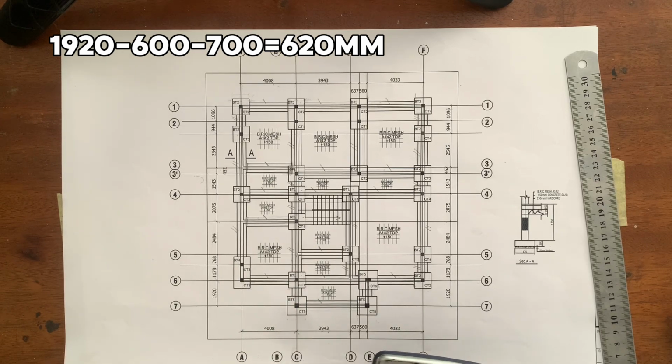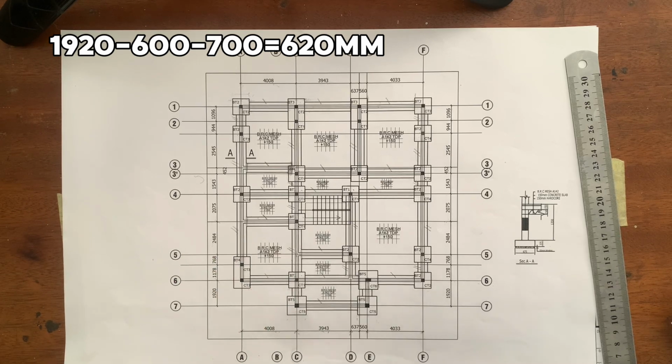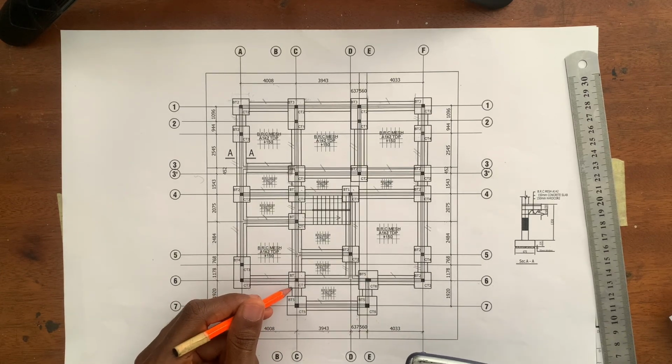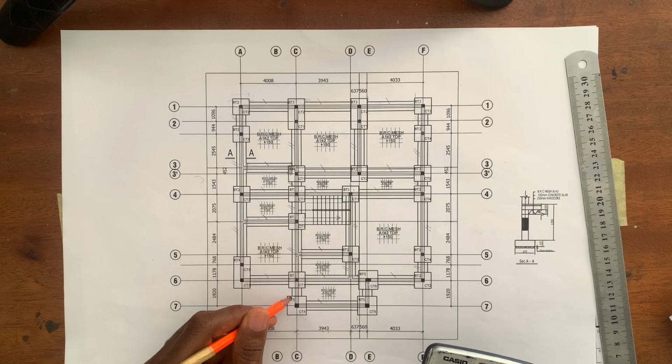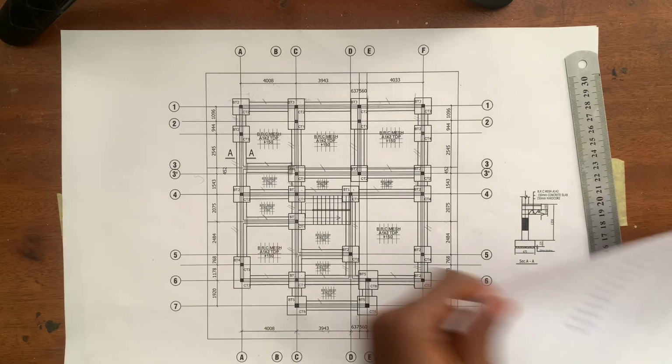So 1,920 minus half of the length of base type 1, which is 600, minus half of the length of base type 5, which is 700, that's going to be 620. It means that the distance from this side of the trench to this side of the trench is 620. So we'll now record it.